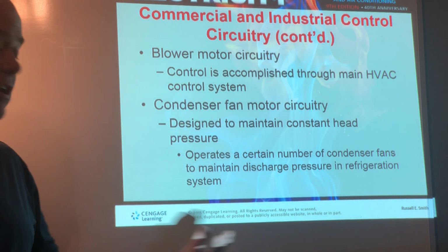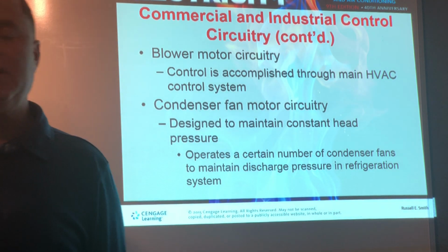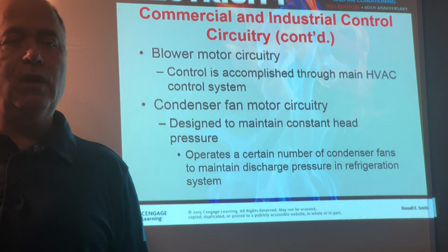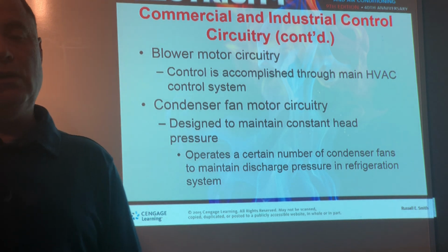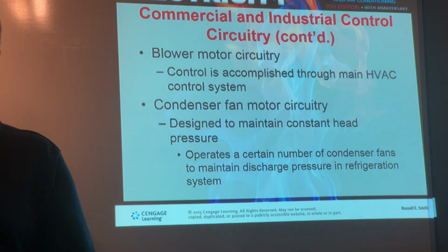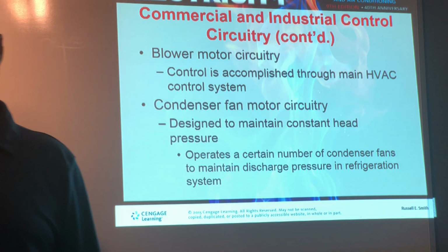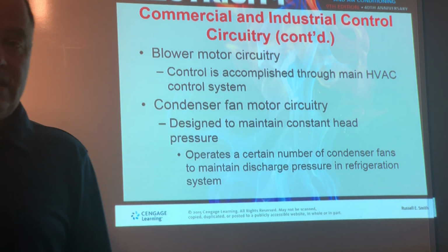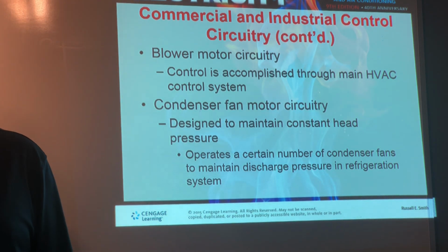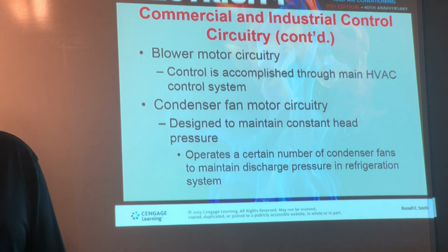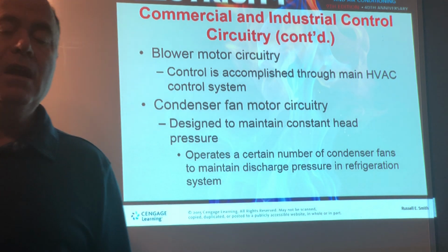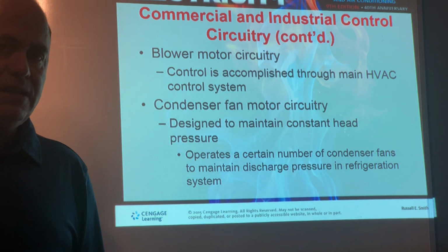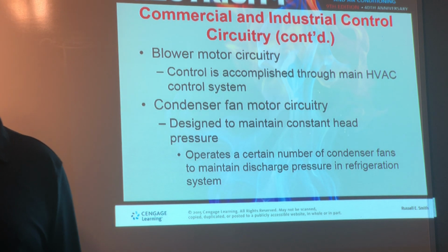So the blower has to be on all the time. Now, the cooling may not be on, the heating may not be on. Maybe they do a night setback temperature where they don't provide as much cooling, or they only cool down to 82 or 84 degrees at night, or maybe they only heat up to 60 degrees when the building isn't primarily occupied. But you're going to have fans running quite a bit whenever people are there, because you need the ventilation, you need to bring in some fresh air, for health and safety.